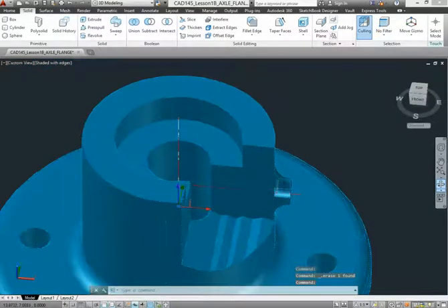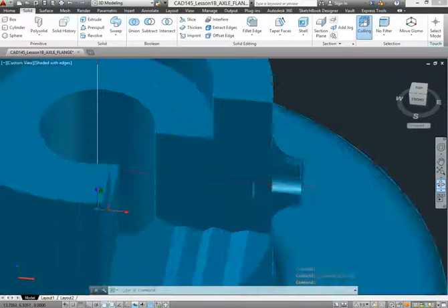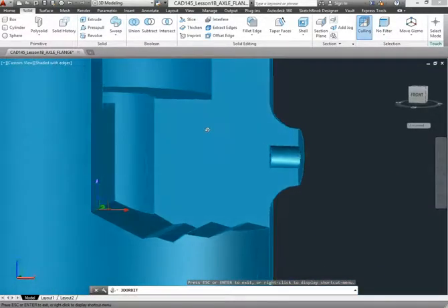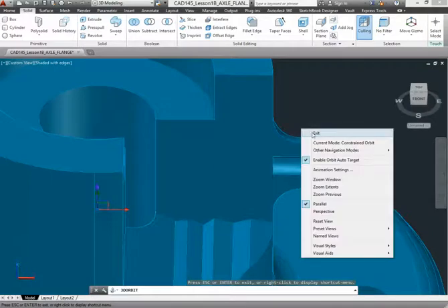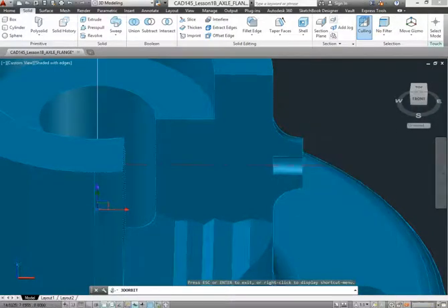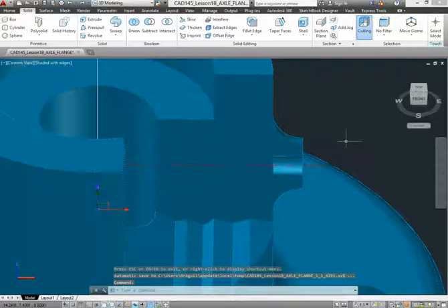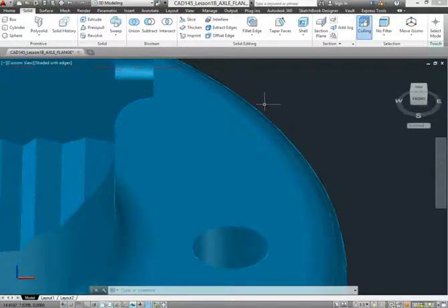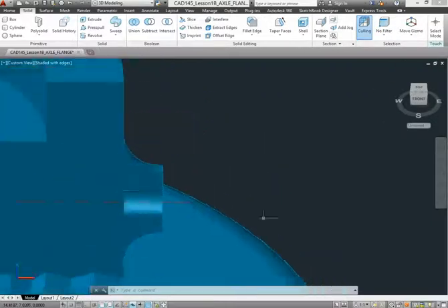The hole did not cut all the way through, as you can see. There appears to be a section that has not been exposed. It's an easy repair. Unfortunately, I had to do it, but I'm going to have to draw a circle, extrude it through, and then subtract it out. That circle is 0.10 in diameter. That's the first thing I need to know.